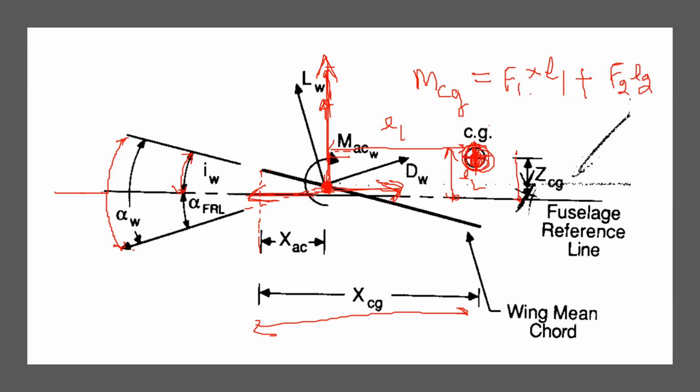And also, of course, you have to keep the sign convention in mind, right? What kinds of moments are considered positive? Pitching up moments are taken as, clockwise, yeah, no, anti-clockwise. Pitch up moments are taken as positive, and pitch down moments are taken as negative. That is just a convention. You can, of course, take the opposite convention, and it won't matter.